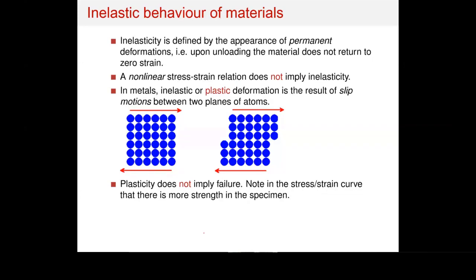first of all, I'm going to talk briefly about the material behavior. If you have this uniaxial test, so you have this bar, and you have some forces applied to this bar. This bar is going to stretch, so the atoms or the particles are going to move relative to each other. As long as these particles return exactly to the original place once you release them, you call this the elastic region. Once there is some relative displacement within the particles, so this layer of particles has moved relative to this one, and this is a permanent deformation, you get into the inelastic region.